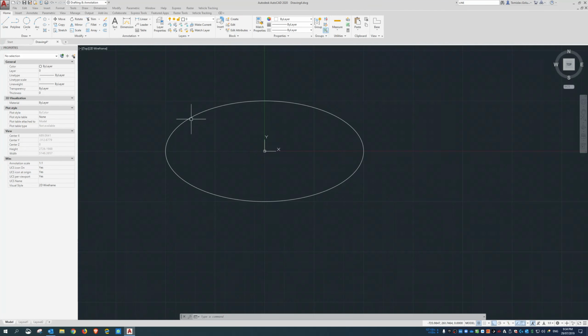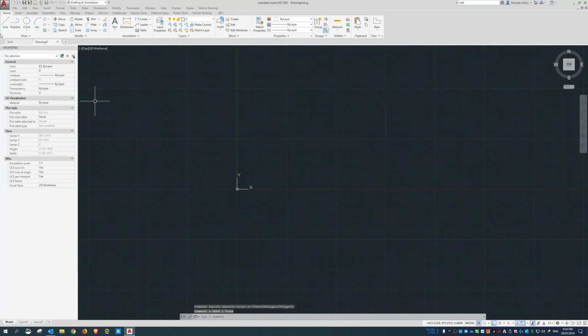Hatching, I'll go through hatching a little bit later. I want to demonstrate all the different things that you can do here. So even something like if I do a polyline from 0,0, and then I can go a meter in this direction, and then you've got A for arc, and then you've got different options down there: angle, center, close, direction. So, whichever way you go.